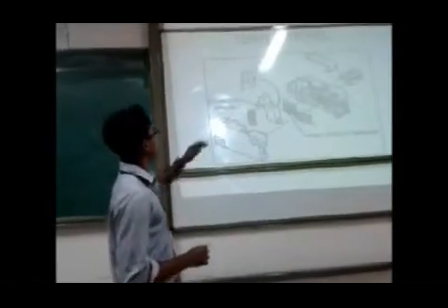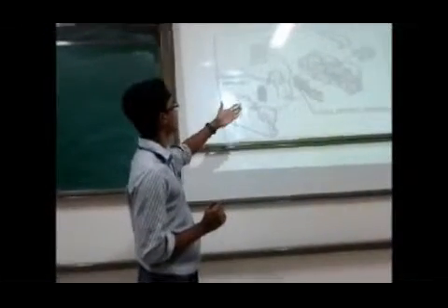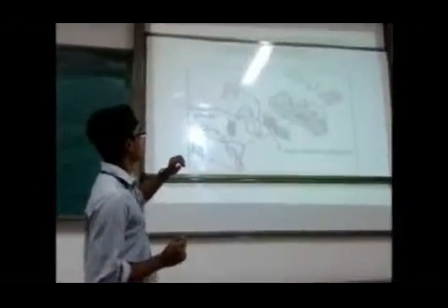And next one is mechanically operated solid state switches. Actually, from the figure, it consists of a modified sensor and a plunger magnet. So the main function is actually when the north pole, for a normal off switch, is nearer to the sensor, it will be in off state.